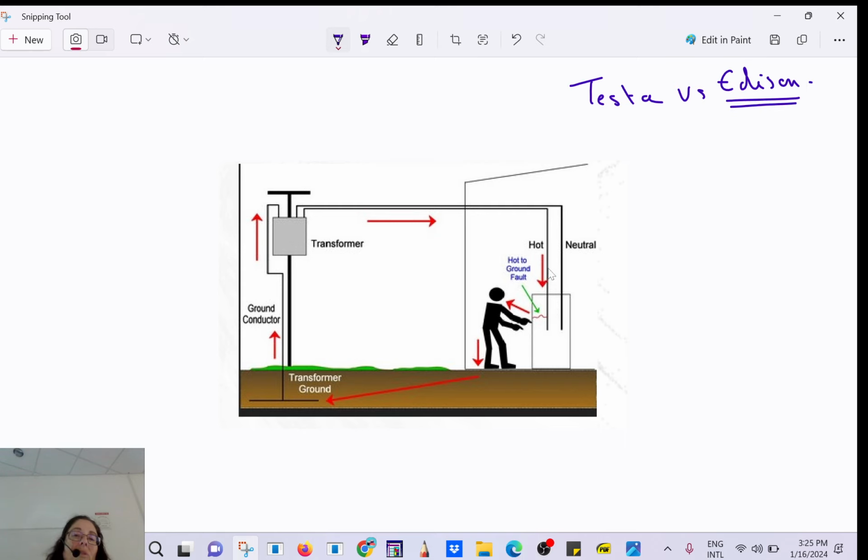So anyway, we don't do that anymore because now we add another wire here that goes to the ground. So if there is a leakage somewhere, instead of going through you back to the base, it will go this way. So it's to protect us. Is that clear? So the hot wire is at 120 volt above the neutral wire or the return path. You see how it works?